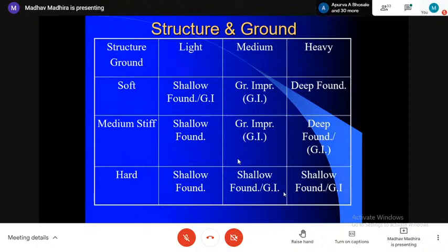Soft is our typical marine soils along the coastline, which have very low strength, of the order of maybe 10 to 12 kilopascal undrained strength. The compression index is around 0.5 to 0.8. Coefficient of consolidation is around 1 to 2 meters square per year. The medium stiff soils are the alluvial soils, which give me easily a bearing capacity of 10 to 15, 20 without any problem.